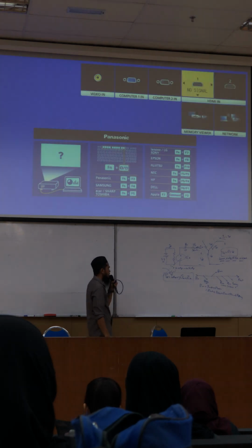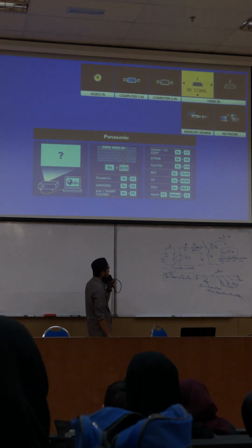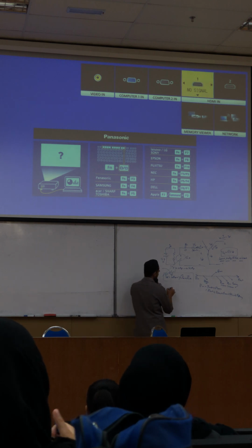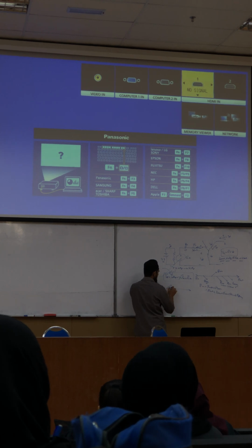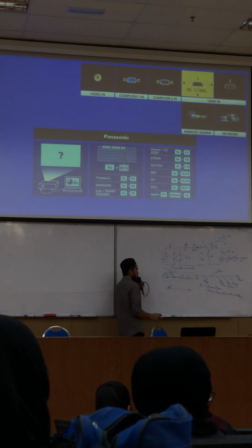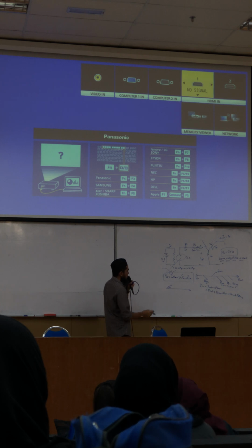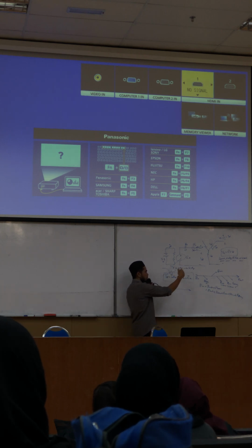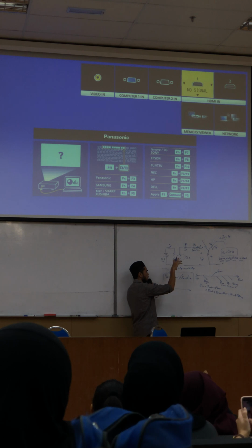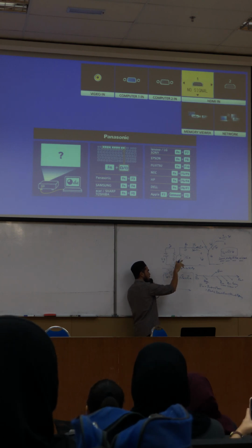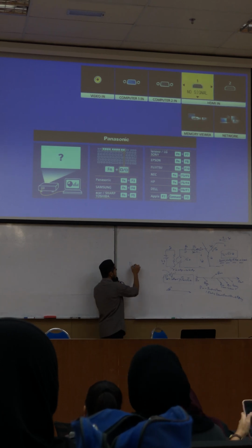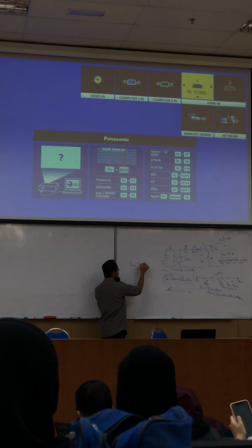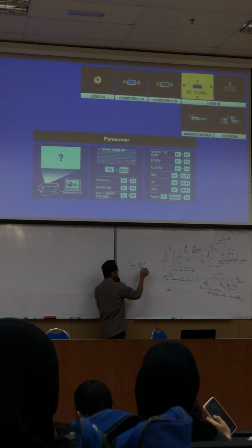Because of the behavior of your synchronous machine. When you start, there is an increment of frequency. But when it operates, it will just rotate at the same frequency as your supply. And N_m or N_s is equal to 120 f over P.